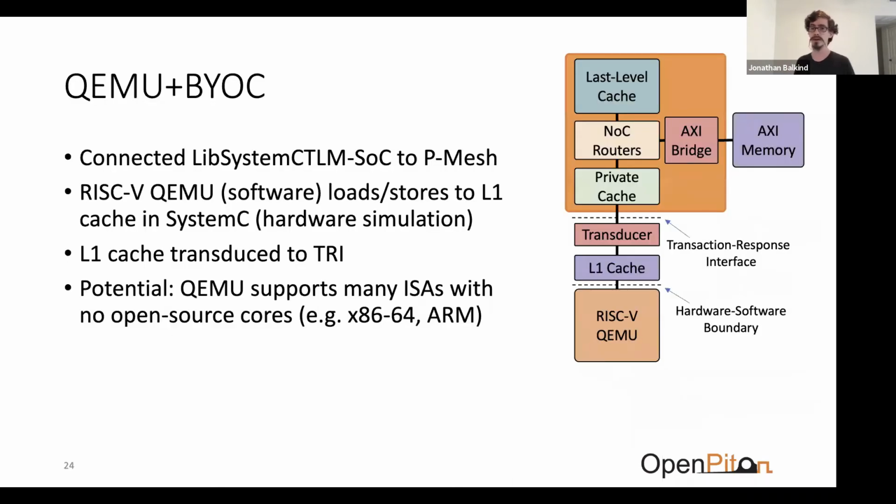So another system that we built: I worked with the developers at Xilinx of a system called libsystemc TLM SoC to connect QEMU to PMesh. So their system can connect QEMU to RTL simulation, and the QEMU will do loads and stores into the RTL simulation, and you can handle those how you want. So we had an L1 cache, we transduced that to tree, and then we had that able to speak to a coherent PMesh fabric. And so then there's a lot of potential here.